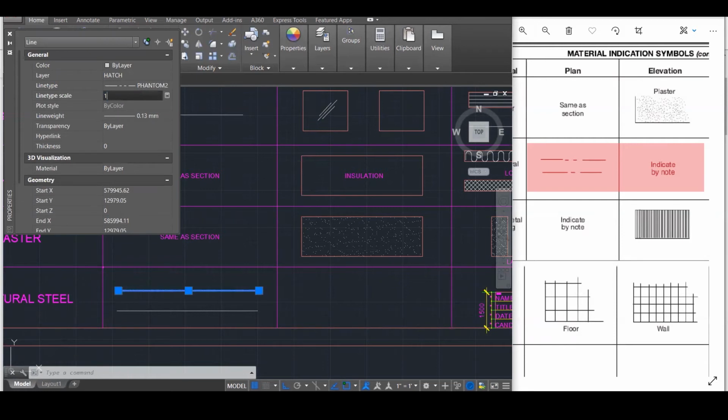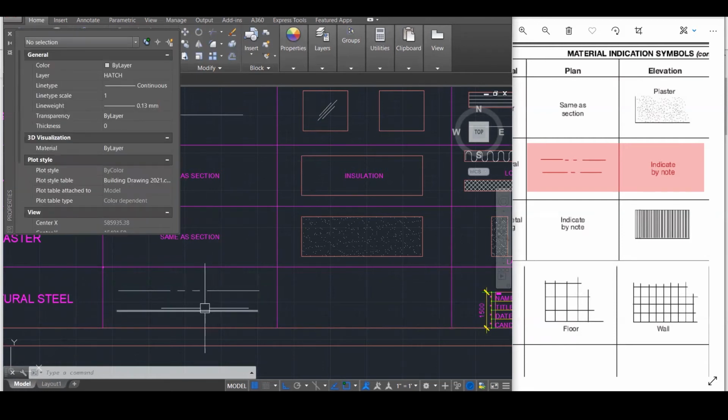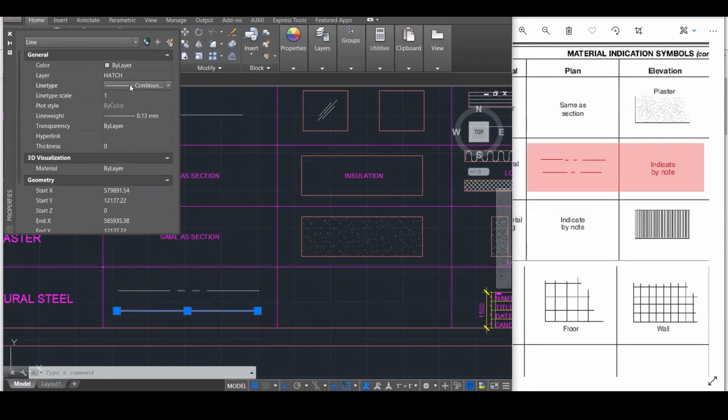And I'm going to change the scale to 100. Yeah, 100 works. Then I'm going to come down here and put this line as dashed. Then I'm going to change this to 100 as well. 100 doesn't work there, so I'm going to change it to 1000. 1000 works, but I don't want not many dashes in my line.